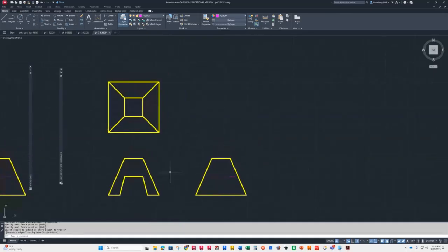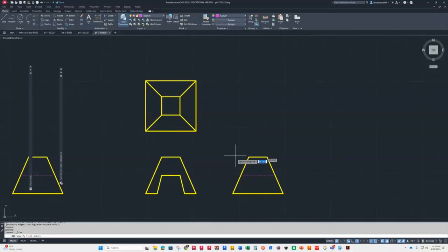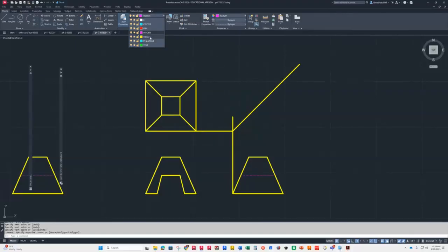So, basically, this is where we were, where we were trying to figure out how to draw the tunnel up there. So what I did is I drew a line from here up, like so, and then you draw a line over to where it meets it, and then you put in your miter line, which is at 45. Okay? So you've got your miter line in there. Here, I'll turn it on. There we go. I'll just put this on so you can see it better.